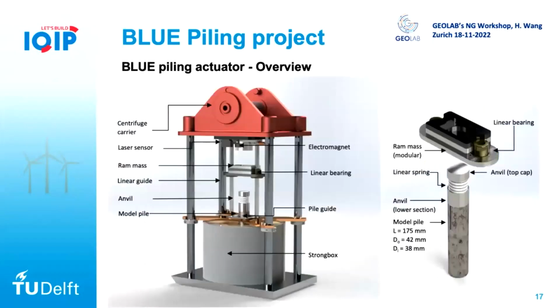And even further, we also developed specifically a hammer system called the Blue Piling actuator. So basically, in between, instead of a buffer, we also put this linear spring to simulate even more, to eliminate more of the bouncing back, to make sure we have more interaction and more energy transferred to the pile.